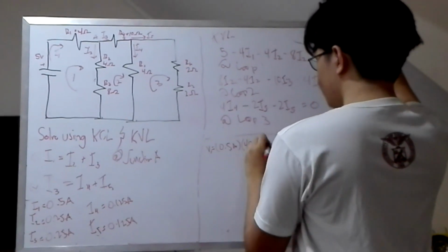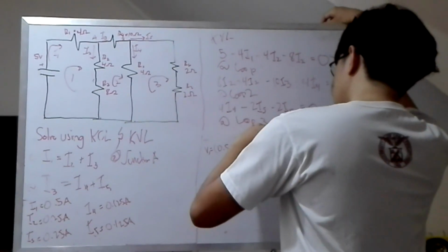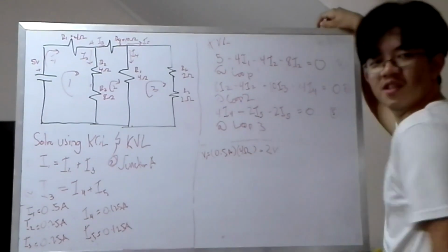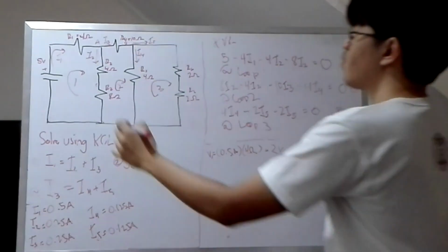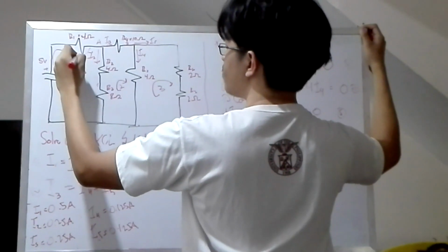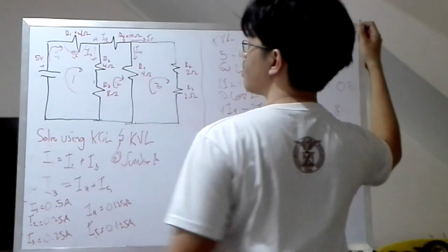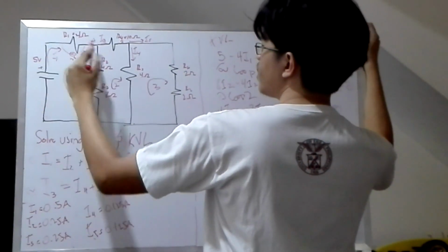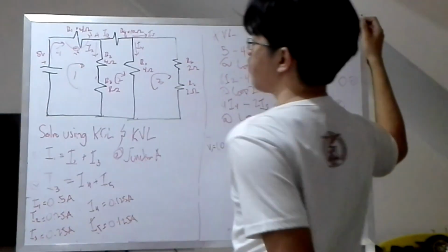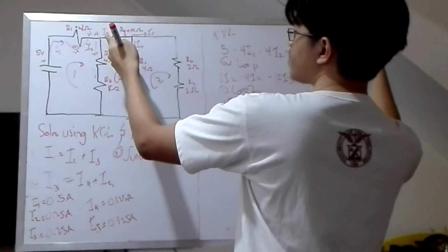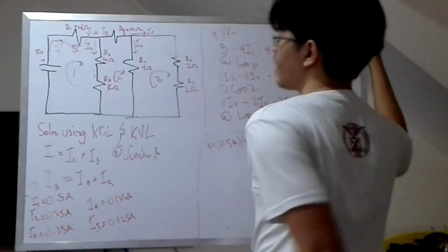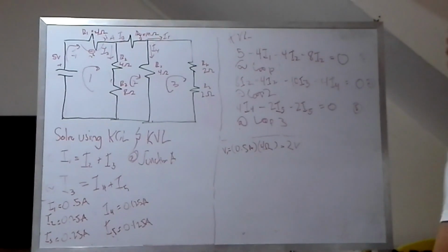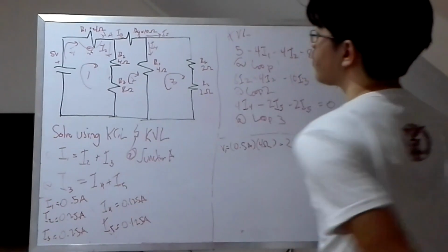So the voltage across R1 would be, sorry, 2 volts. So there's a voltage drop of 2 volts here. Since it's 5 volts here, you get 3 volts here. So there's 3 volts going here and going there, since they are in parallel.